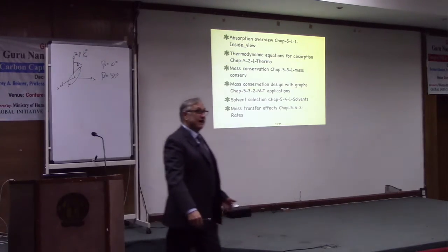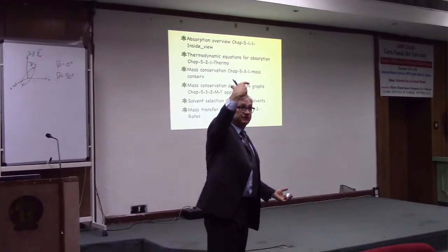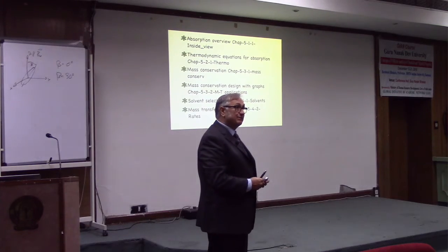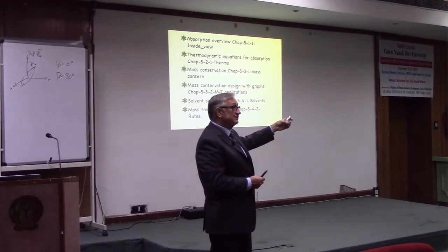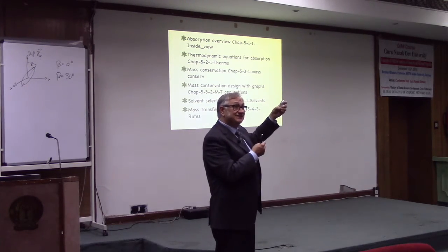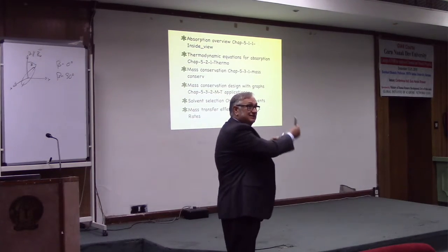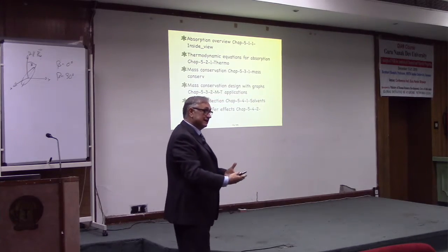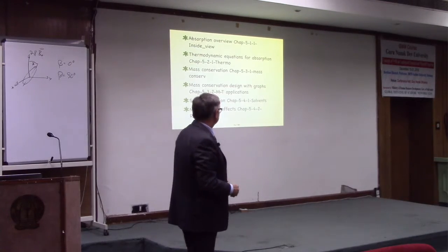And remember, there's a graph, y-axis and x-axis. The y-axis is the composition of the vapor. The x-axis is the composition of the fluid. The equilibrium line starts at 0, 0 and goes straight. And the operating line, which is the concentration of mass, is another straight line, and it's above the equilibrium line. And you use those two lines to draw triangles that represent the contact between the gas and the fluid in each one of those stages. It's a tool for doing absorption.